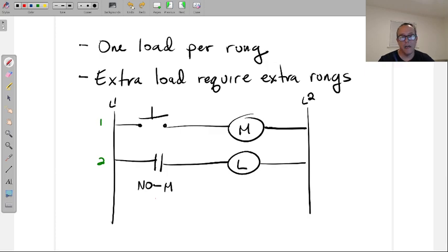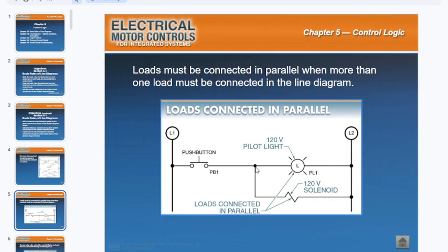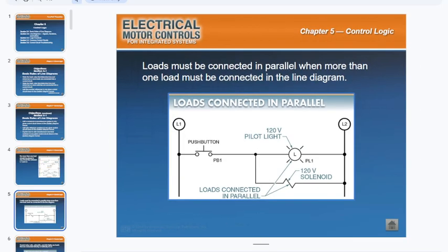Now, the benefit, I would say, and here's my reason. Anytime I'm starting a second rung, I like to start the rung from L1. I do not, as much as I can possibly avoid it. All right? Unfortunately, in the case of the one in the book, I cannot avoid it. But as much as I can possibly avoid it, I try not to start the circuit from the center of a rung. And there's a reason for that.